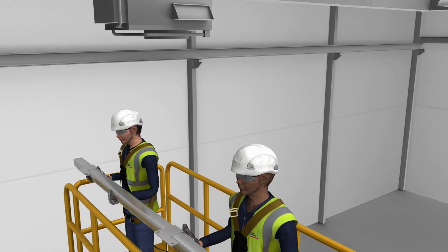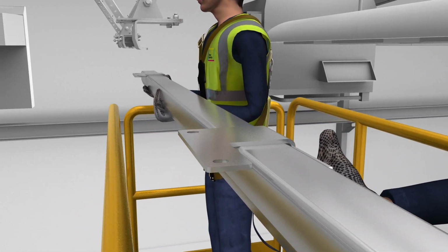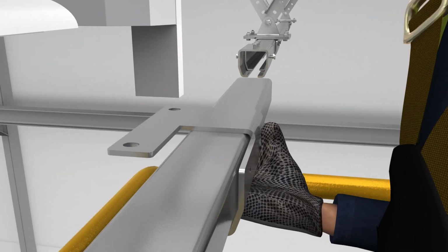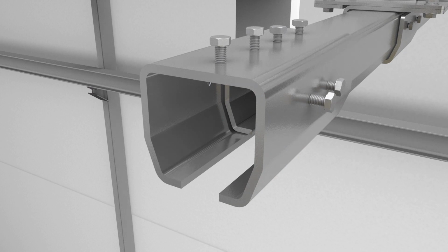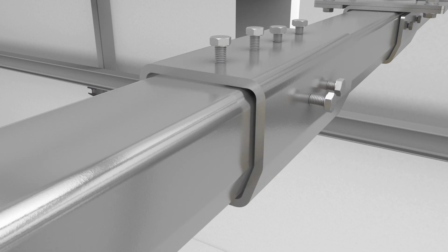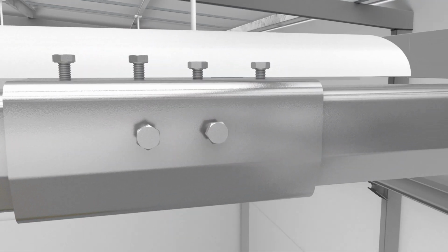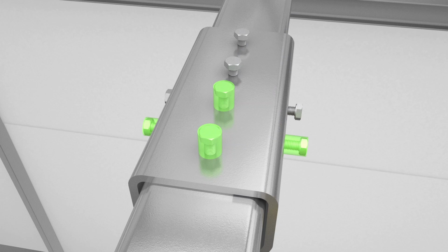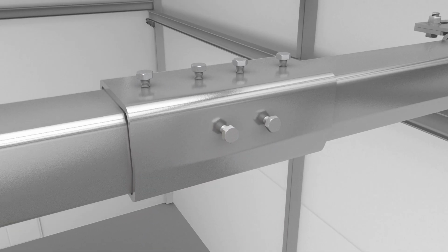Following the procedure for rail insertion and securing, install the next section of rigid rail into the respective clamshell assemblies. Prior to tightening the clamshell pinch bolts, slide the rigid rail through the clamshells into the open end of the rail splice. The two adjoining sections of rigid rail should touch one another within the rail splice. To secure the subsequent section of rigid rail, carefully tighten the additional pinch bolts that are located on the rail splice. Care should be taken to ensure the additional pinch bolts are only tightened sufficiently to pinch the rigid rail during this step.